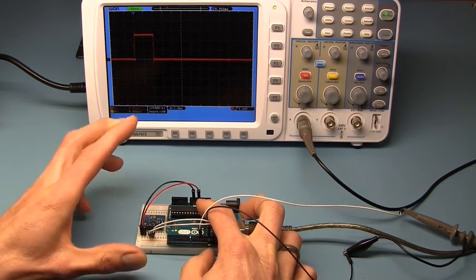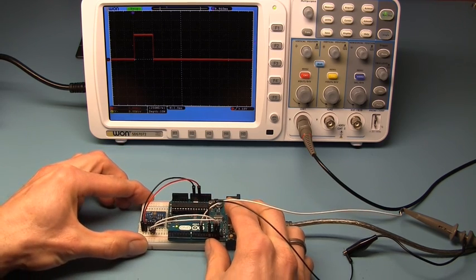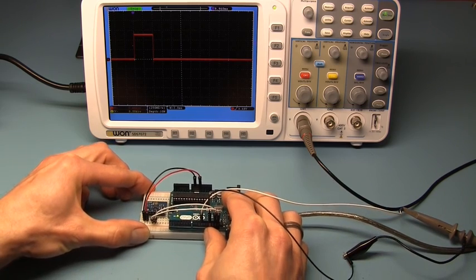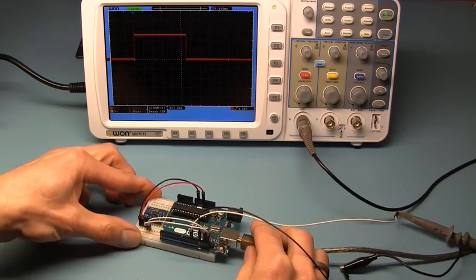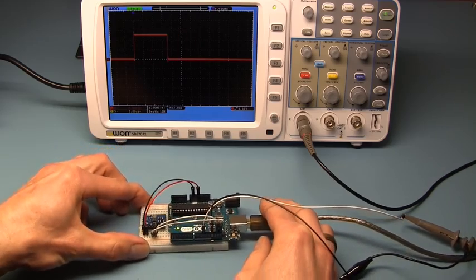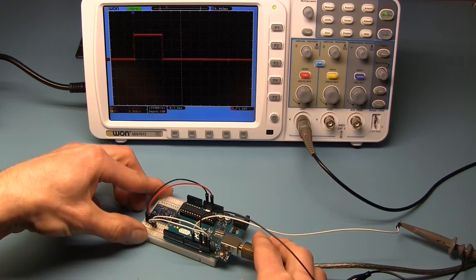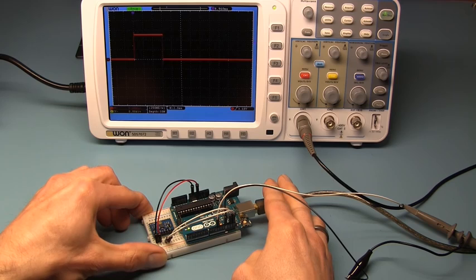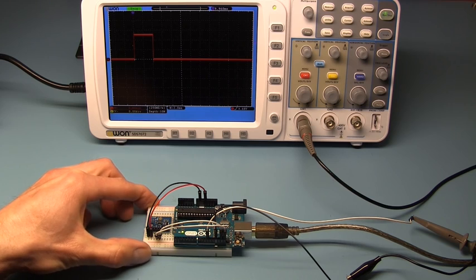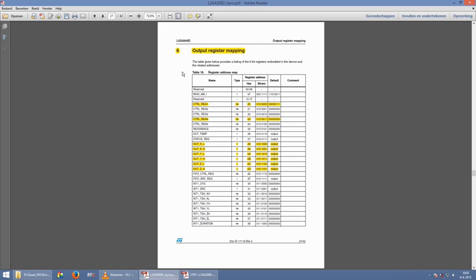Now, because the gyro only senses rotational motion, its output will not change if I tap on it or shift the gyro without rotating it. As stated in the manual, the gyro output is an angular rate. This means that the output is 0 when the gyro is stationary. With a different angular rate, the length of the pulse will change proportionately. Because we only need to correct the unwanted movements of our multicopter, the gyro is the ideal sensor for our project.